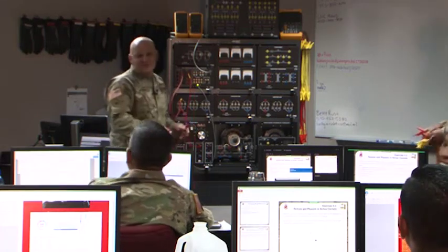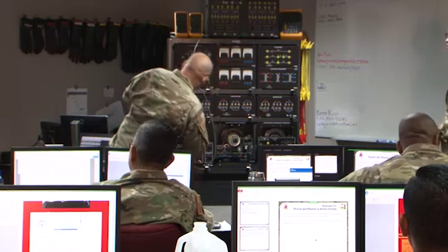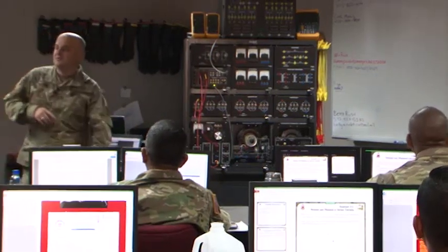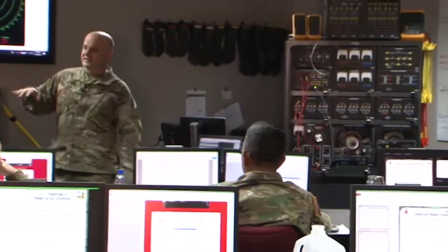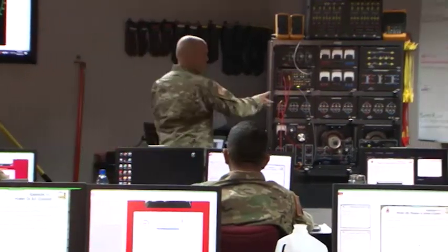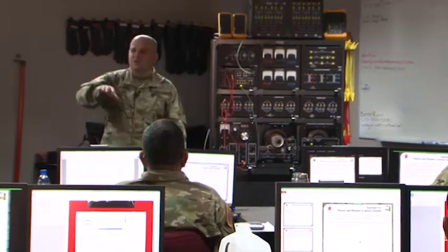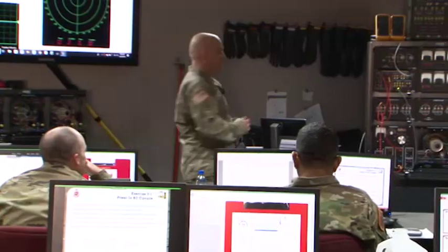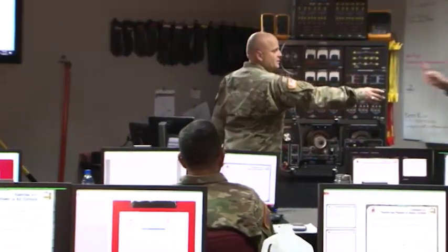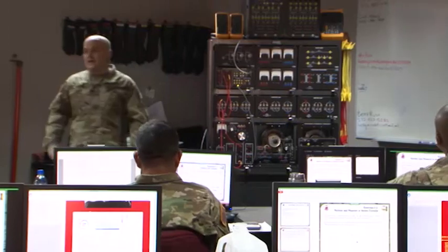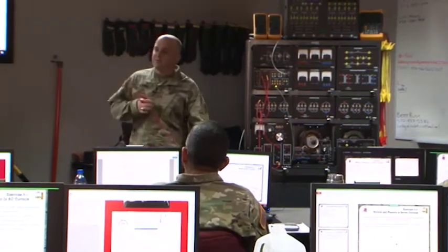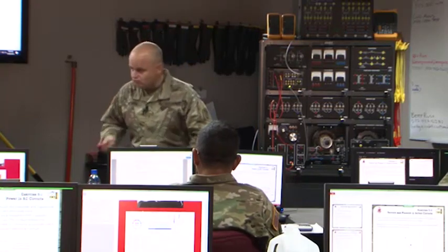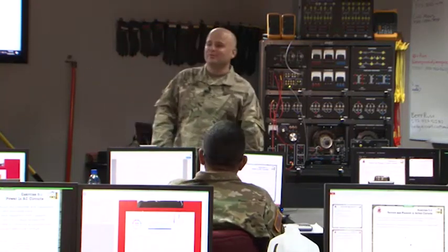What? Gold star removed. You got to work back up now, buddy. All right, so what I just set up is the current metering and the resistor in the circuit, right? Now I'm going to flip these switches, all three of these, because the equivalent resistance of a 1200, 600, and 300 ohm resistor comes out to 171 ohms, right? We know that. Now, give me a red one, please. All right, so now I'm just going to meter the voltage across my one piece of the load.